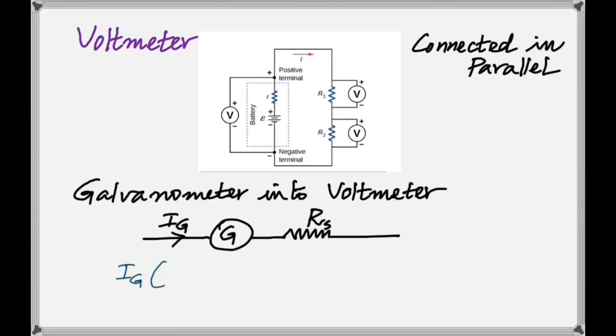So that's where it's called RS for obvious reasons. And you have that tiny current that comes in through the galvanometer. How do you know that current is going to be small? Because the total resistance of these two is going to be high, isn't it? Because this is a very high resistance. So now the voltage is simply that current multiplied by the sum of the resistances. So Ig, now Ig into that total resistance, and then rearrange this to give that. So that's how you calculate the resistance that is to be connected to convert it into a particular voltmeter.